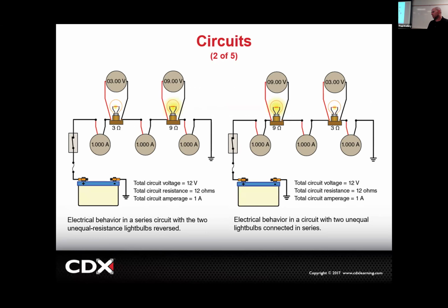It's an unwanted resistance. So we learn a lot on these boards using multiple bulbs that kind of simulate unwanted resistance. It's hard to really duplicate unwanted resistance because it would take time. You'd have to get some connectors to put on these boards, and then I'd go leave them out all winter long and then bring them back in and be like, perfect. And then it would make a bad unwanted resistance, but then by the time you disconnect and reconnect it 100 times, it'd probably clean the rust off, and then it'd be like, it's time to leave them out in the rain again or something, right? So we'll use the bulb a lot of times as a way that you can understand what an added resistor will do to the circuit.